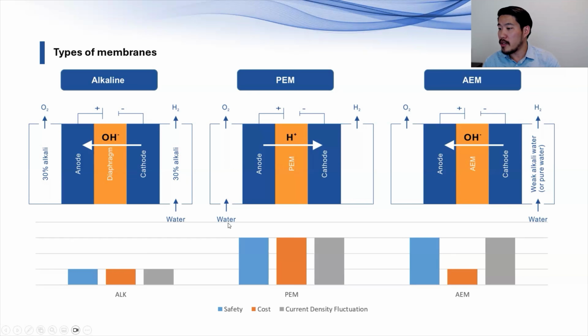We moved on to proton exchange membranes, which most folks are trying to use and which you see mostly in the market now with the different fuel cells and electrolyzers. The way this works is a little different. The water comes in, oxygen actually stays on this side, and then as it hits the anode, the hydrogen goes through and reaches the other side.